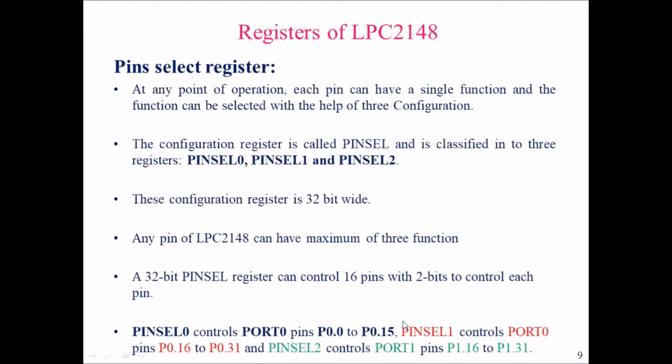Likewise, the second pin select register, pin select 1, again will control port 0 pins, from port 0.16 to port 0.31. So these pins are controlled by pin select 1.